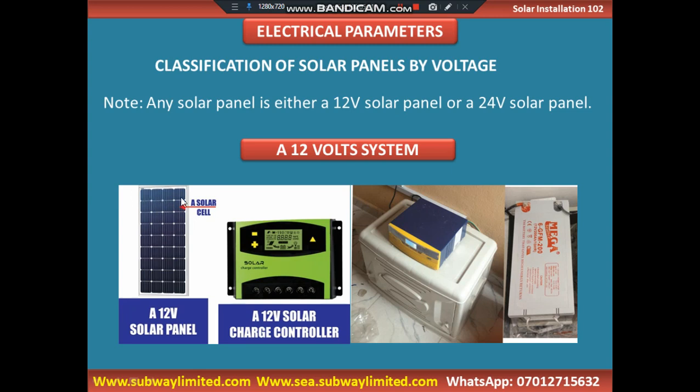If you count these cells here, you will notice that there are 36 in number, and each of the solar cells here is 0.5 volts or 0.45 volts. And if you connect this in series, you will certainly have a voltage of between 15, 17 or 21 volts, depending on the intensity of the sun.